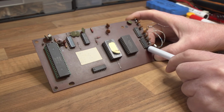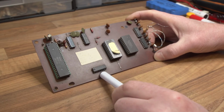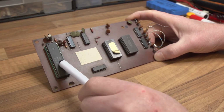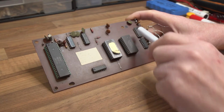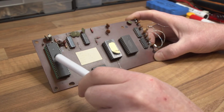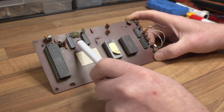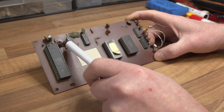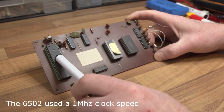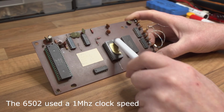So that's the in-out section, that's the RAM, that's the ROM, and we've got a chip here, and that's the decoder, which takes the address from the microprocessor and segments it, if you like, switches, either puts on the I/O section, puts on the RAM, or puts on the ROM, depending on the value coming through the address bus. And up here we'll have a little bit of TTL logic for the clocking circuit. That's the clock with its little oscillator there, and the clocking arrangement then drives the clock input, which internally clocks the program counter, if you remember, to read the values from the firmware.